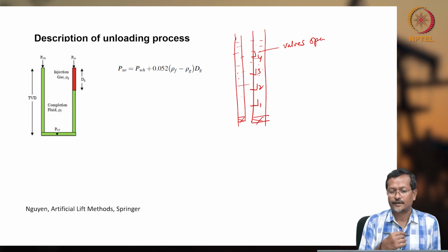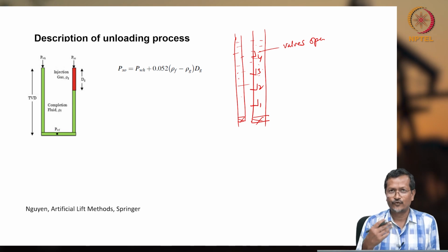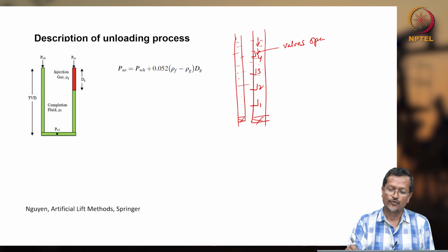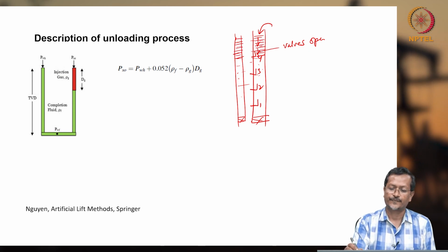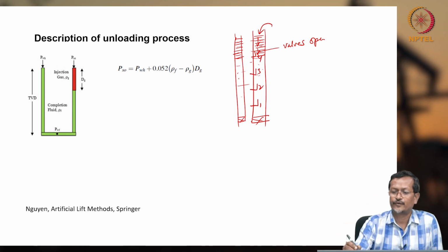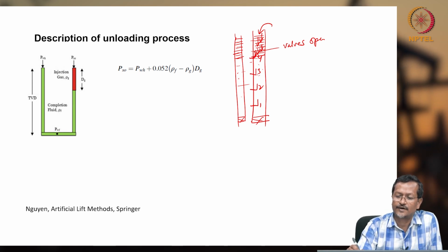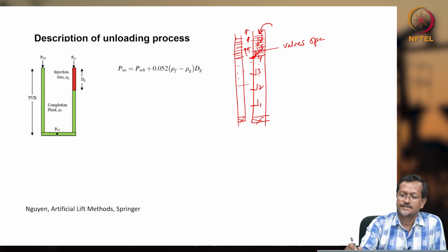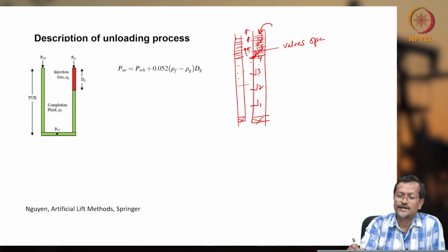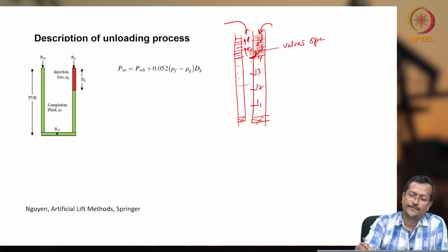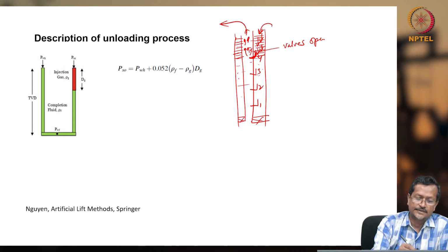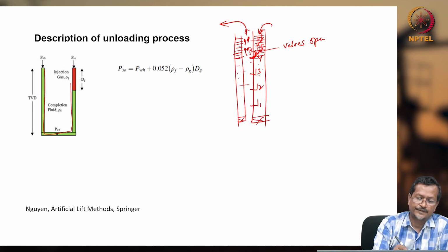Now, when you are unloading a wellbore, you are removing this kill fluid. How? Gradually you inject gas from the surface and remove the fluid in the casing area, because you are injecting from the annular area. You inject very high pressure gas and gas will be entering through this valve, and liquid will be going out. So this time, when you first inject gas, gas is not entering your tubing; rather the liquid inside your annular area enters the wellbore and goes out. To resemble this, they have made a concept like a U-tube. You can see one system is like this.